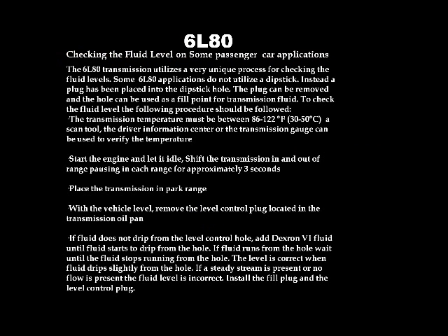Checking the fluid level. When it comes to checking the fluid level with this transmission, some of the applications like the trucks will actually have a dipstick. But a lot of the passenger cars don't physically have the room in the application for a dipstick. So what they will do is put in a plug, and then they have what basically becomes a standpipe in the transmission oil pan itself. Now when you're dealing with one of these, it's very important that you're at the right fluid temperature when you pull the plug out of the standpipe hole. If you do not do that, you're going to have this transmission either overfilled or underfilled.